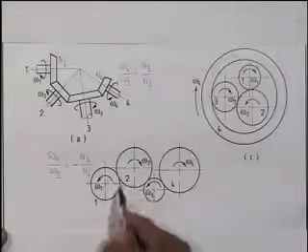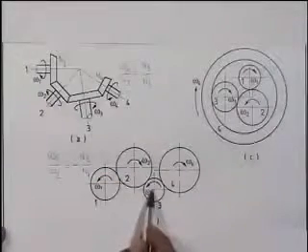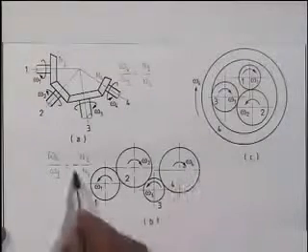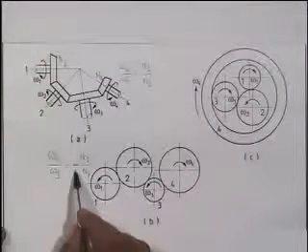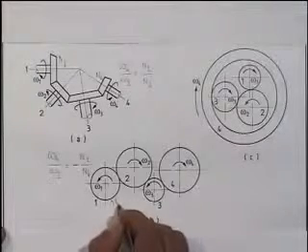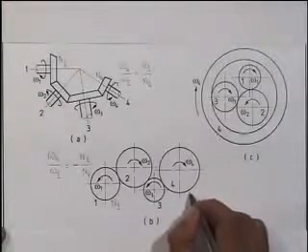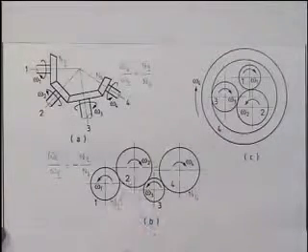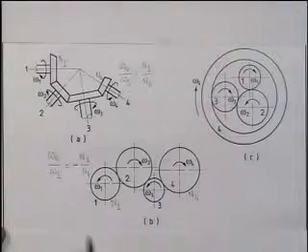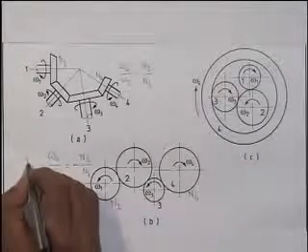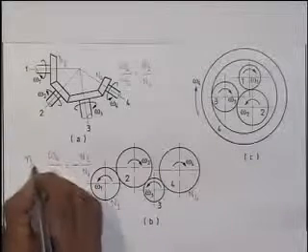With one intermediate shaft we have done earlier, they rotate in the same direction, but as soon as there are two intermediate shafts we get the opposite direction, that is a negative sign. Right, N1 is the number of teeth on this gear and N4 is the number of teeth on this gear. Number of teeth on the intermediate gears do not matter. Very often this angular speed we write in terms of RPM and I will denote by small n.